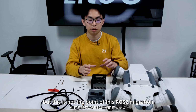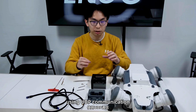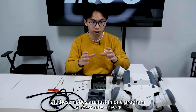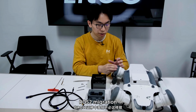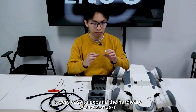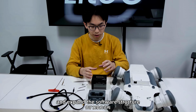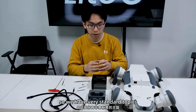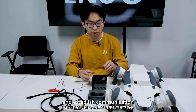of this ROS2 migration. We already have a Lite3 RL deploy using UDP communication. All these nodes are just in one program. We don't have to do this ROS2 migration. So the best advantage of ROS2 migration is that it is very easy to expand the hardware and expand the software structure. So we have very standard topics, and we can just subscribe and publish to that topic and establish communication.